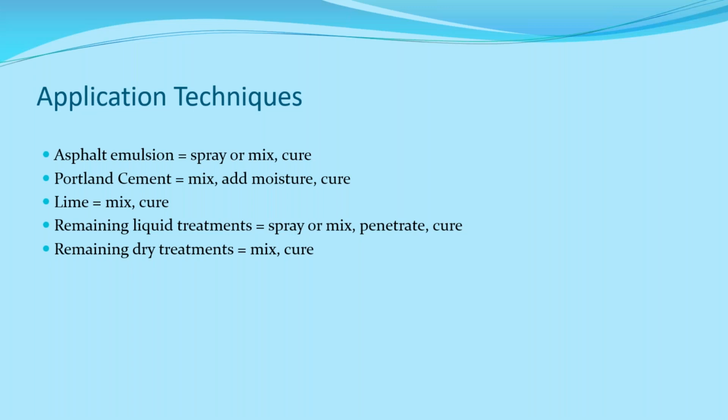and your surface temperature starts getting up around 110, you may not want to shoot your magnesium chloride or calcium chloride on your roadway, because what ends up taking place is that it loses its moisture too fast, and it doesn't allow the salt to penetrate your roadway very well. So you may want to do that type of treatment if you're expecting some real warm weather early in the morning, or maybe late in the evening after the roadway cools off a little bit.